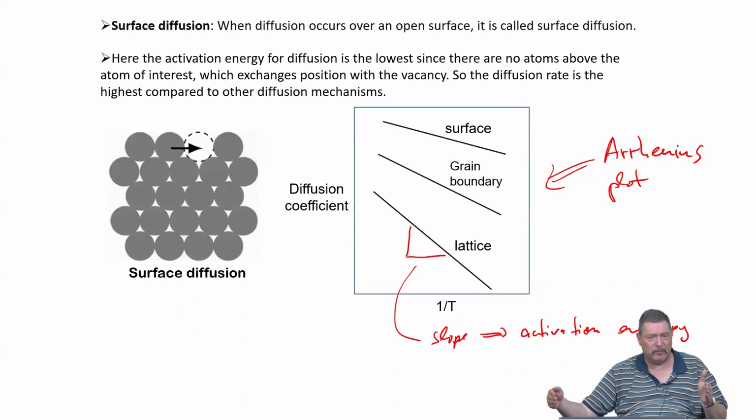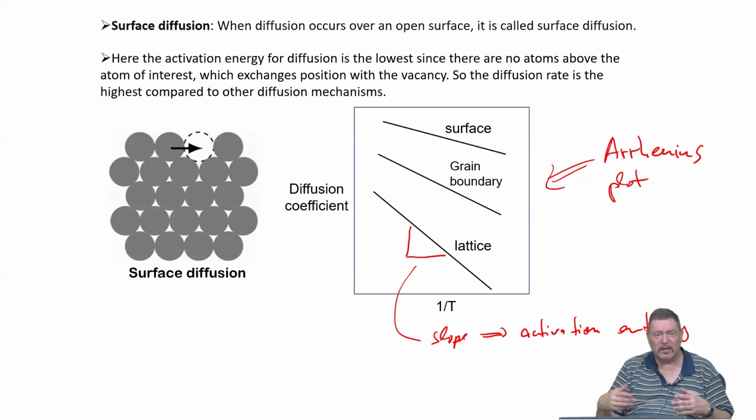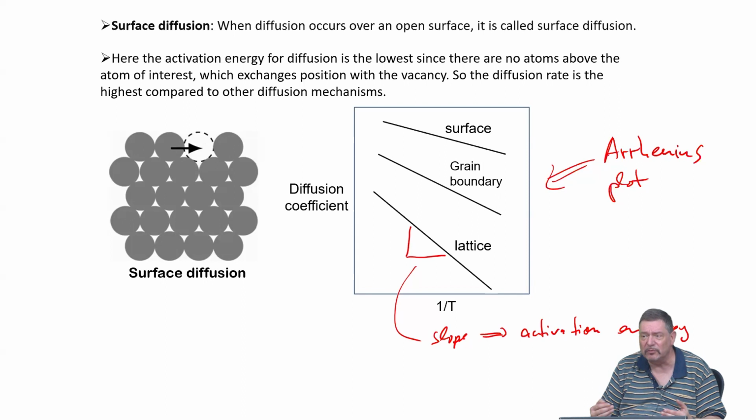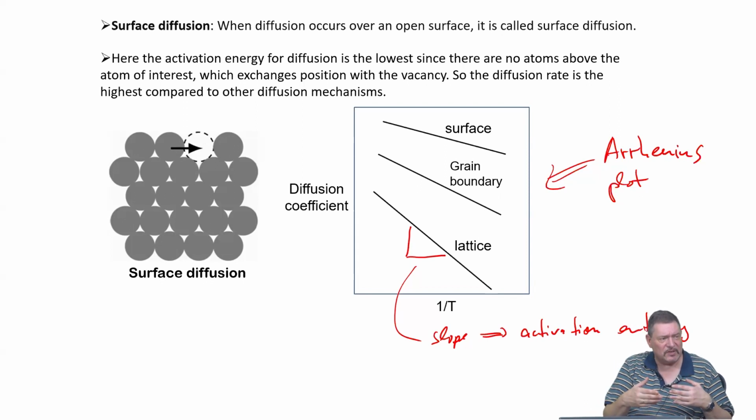And this is the beauty of diffusion experiments. If you plan them in a systematic way, you can select ahead of time which type of diffusion you want to analyze. And this is how it's done in the experiment in reality. So you can deconvolute experimentally. You don't need to do all of this mathematically. There are just some processes which do not have such a large contrast, like for example, phase boundary diffusion and grain boundary diffusion, which will occur at almost the same diffusivity. So there is not really a window where you can select only one of those, then you have to do the proper math.